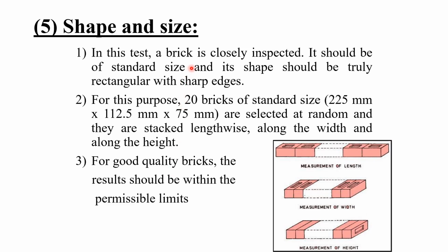Shape and size. After manufacturing of bricks, are the bricks formed in the standardized size or in a good size? For that purpose, the shape and size test is performed. In this test, a brick is closely inspected. It should be of standard size and its shape should be truly rectangular with sharp edges. How do we do that test?